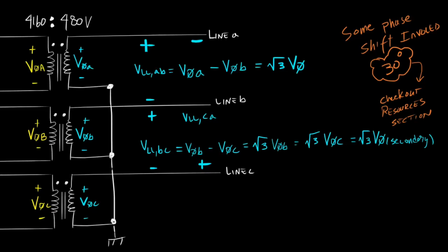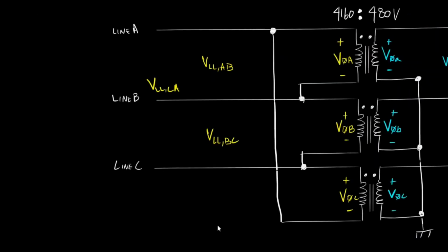When I was first learning this, it helped me to visualize this relationship between the line-to-line voltage and phase voltage when looking at actual numbers. If we took a super duper voltmeter and measured across line A and line B on the primary side of our transformer, we should expect 4160 volts. This is our line-to-line voltage that we assumed in part 1.